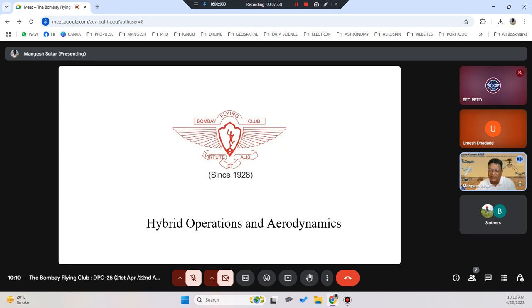What happens when, let's say, we take an example, pitch forward? When we say pitch forward, we are giving a push to our right stick. So what actually happens? How does the drone make that movement? Any idea? Have you thought about it? Up front, the CW and CCW motors increase the power, and the back motors lose the power.